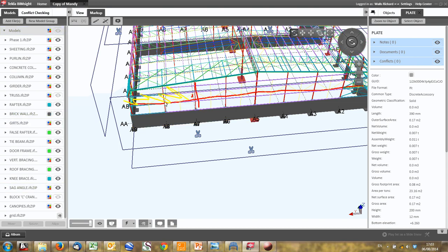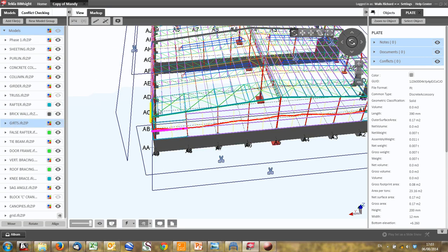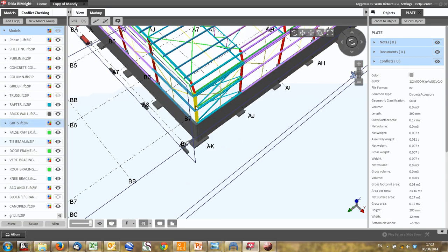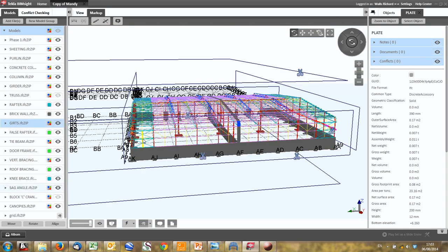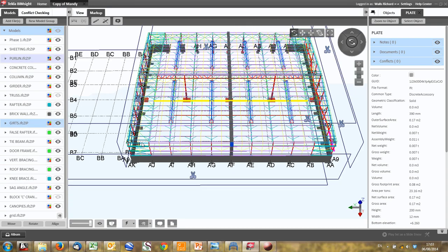If it's a statically indeterminate structure on top, you won't have it with fixities. Obviously, if this is, it might attract a bit more load to the center. But roughly, you can calculate that reaction simply by taking a quarter of this face or an eighth of this face. Apply it all at that point, and you can get that load straight away. But remember, once again, that's only for this face. Whereas if you have suction pressure acting at the same time on this face, that will pull this, and you'll have a load from that same area on this side. If you only have one brace bay, let's say only this brace bay or this brace bay, you need to add pressures from both sides, as I keep emphasizing.